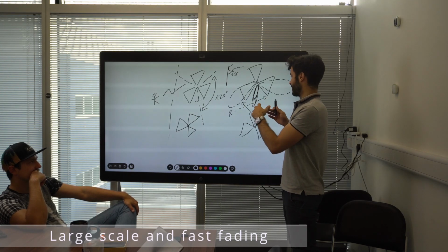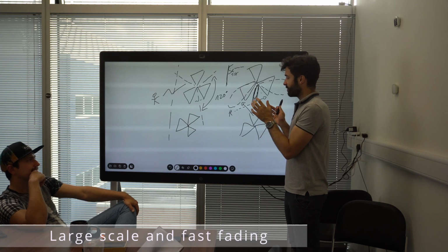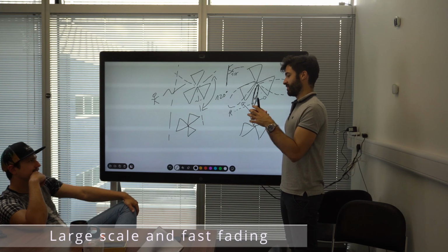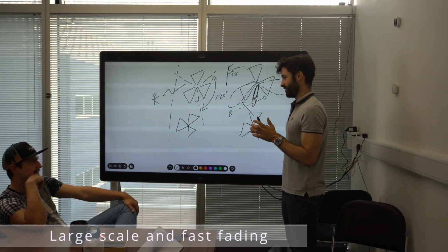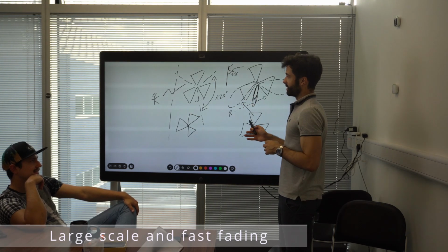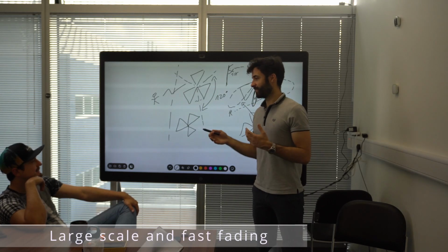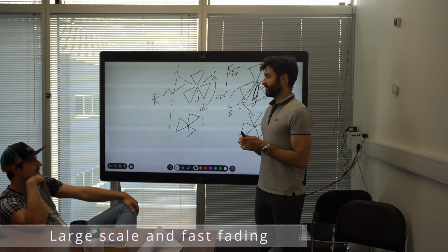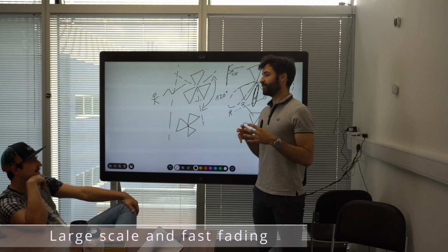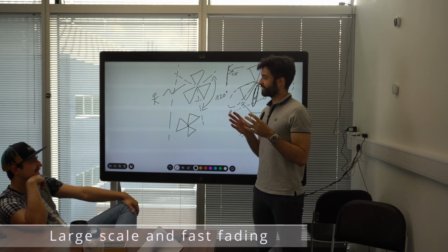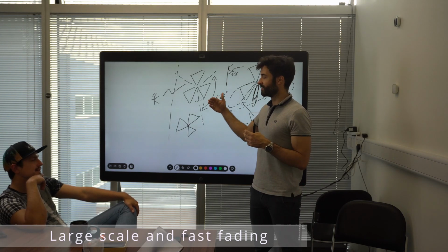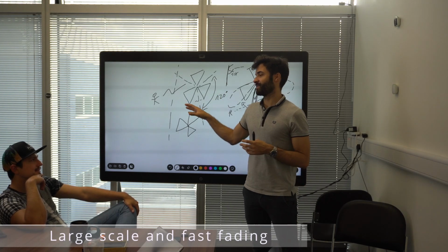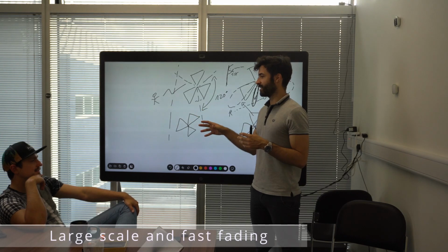And I was saying that even when we increase the number of base stations, we play with the frequency, we play with the tilt, so we have lower ranges of the cell. But because of these attenuations that I just explained, the fact that you reduce the cell range doesn't mean that you proportionally reduce the interference, because you have these variations in the signal that many times are classified as random.